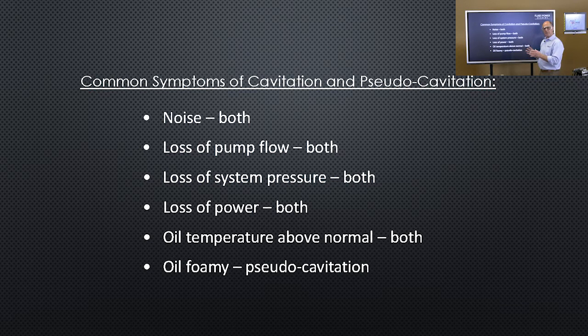So there's a difference, and one is visible. If I look at my sight glass on my hydraulic tank, for example, and I see foam in the sight glass, this is indicative of pseudocavitation. So cavitation has everything to do with the dissolved air in the oil and a liquid's vapor pressure. Pseudocavitation has everything to do with air going into the inlet side of the pump from an outside source.